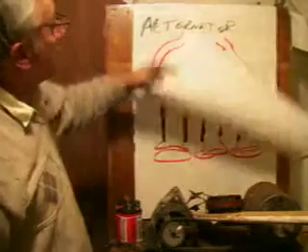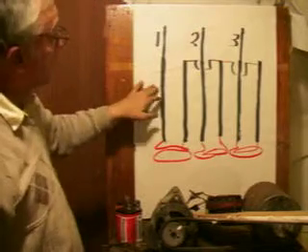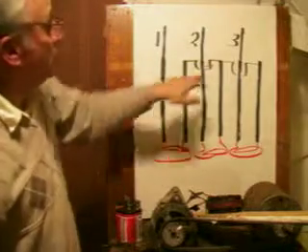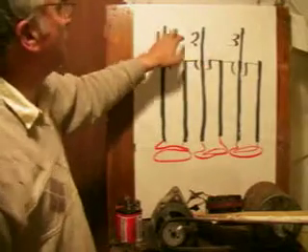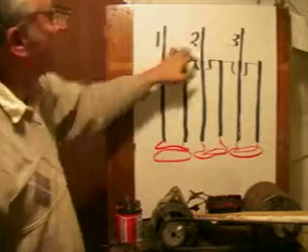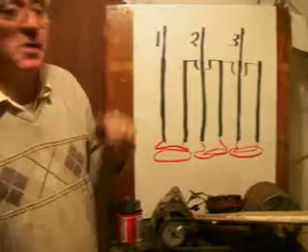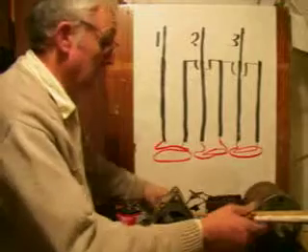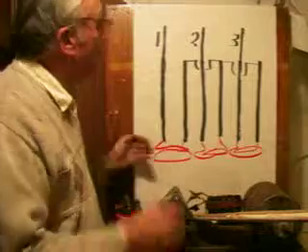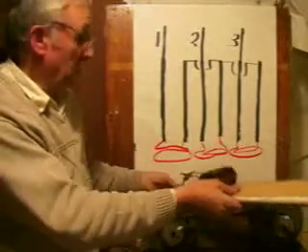So what you can do, however, is join 3 of the wires, 1, 2, 3, and use that as a neutral, and then you can use the 3 phase wires for your power. You'll see that if you watch in country areas, 3 wires coming out, and they're tapped then for individual households, or they can all 3 go into a factory if you need motors. So where motors or a big transmission of electric power is needed, the 3 phase system has become the norm.